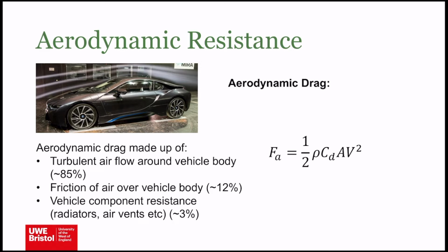That's the projected frontal area. Okay, so you take a photograph of the car at the front. Okay, and you trace the shape that's looking at you. Okay. So obviously, I mentioned how big the tyres are having an impact on aerodynamics. Well, wider tyres will give a bigger projected frontal area. Okay, so obviously that's the thing that is impacting you. So obviously something that's very narrow, okay, like a vehicle with tandem seats perhaps, obviously a much smaller projected frontal area. So often it's this CdA value that's the big factor, the aerodynamic drag, the drag coefficient times by the frontal area.